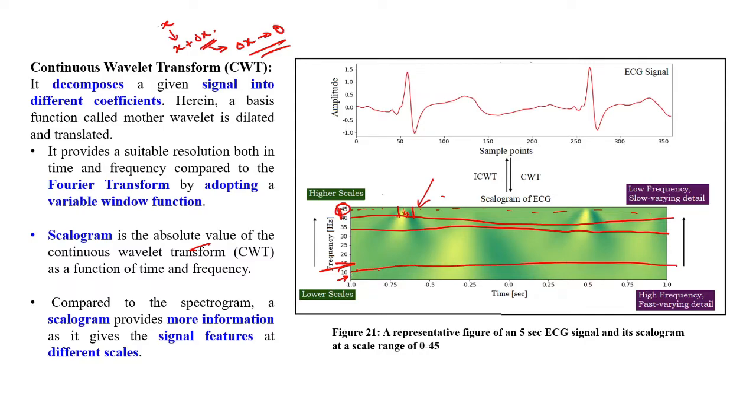So over here, in the 0 to 10 frequency band, if you look over here, we are losing the time resolution. However, if you go towards the higher frequency component, we are able to see the signal component in a confined zone. यहाँ पे देखो काफी एक broad सा you are getting the information. However, in the high frequency zone, you are able to confine the thing.